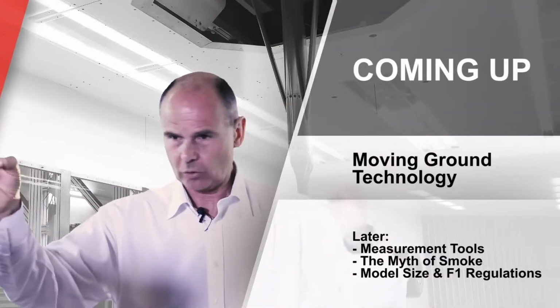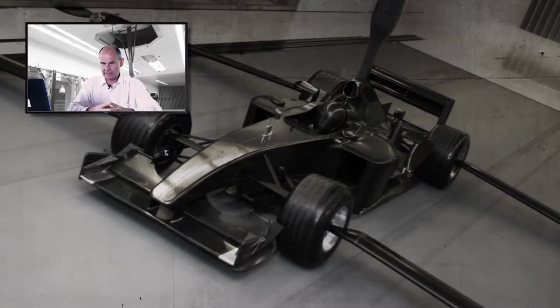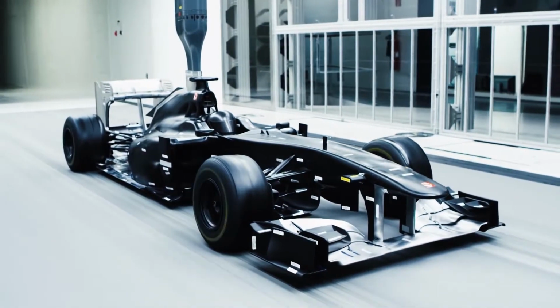Mount systems for wind tunnel models of race cars, we've tried every type of mount that you can think of. Wires suspending the model from above, which is quite difficult to manage, not particularly rigid. It's a technology we'll probably investigate again in the future. A sting coming into the tail, like the aircraft industry, we've tried. Mounts either side of the model, mounting the model from arms on the wheels, and in the end, the system that appears to give the least overall aerodynamic interference into the flow around the car is to mount it from above, somewhere around the middle of the model. It's not that we haven't tried other methods, but it's about the best way.